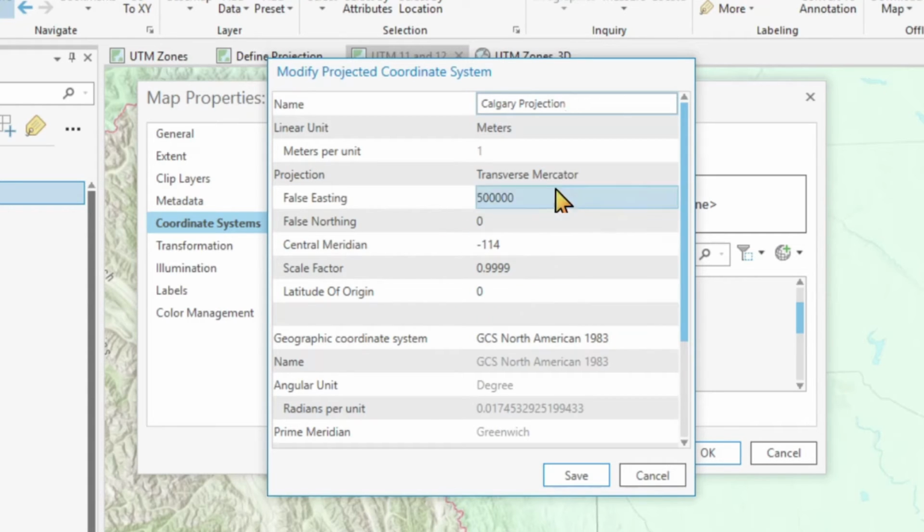They adopted that. However, instead of using a false easting of 500,000, Lethbridge uses a false easting of 0, because we don't have to deal with negative values and the city extent is not very large, so we get away with this. The only problem with that is that it is breaking the convention that UTM zone-based projections always have a false easting of 500,000.